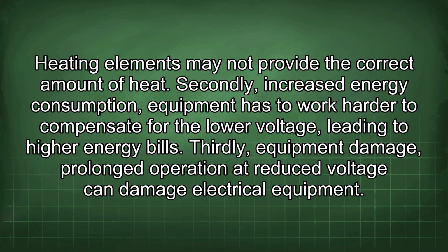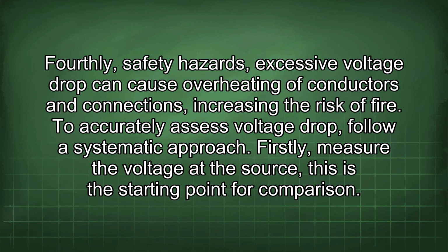Secondly, increased energy consumption. Equipment has to work harder to compensate for the lower voltage, leading to higher energy bills. Thirdly, equipment damage. Prolonged operation at reduced voltage can damage electrical equipment. Fourthly, safety hazards. Excessive voltage drop can cause overheating of conductors and connections, increasing the risk of fire.